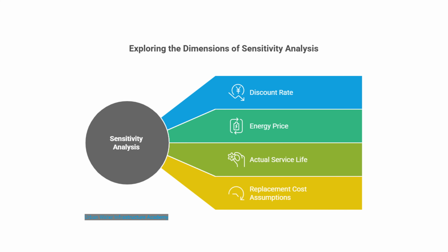Sensitivity analysis. What could change the outcome? LCC results are sensitive to discount rate. Higher rates reduce the importance of future costs. Energy price. Rising energy price increases the advantage of energy efficient assets. Actual service life. If pump A lasts longer or pump B fails early, results may shift. Replacement cost assumptions. Future cost changes directly affect PV results.